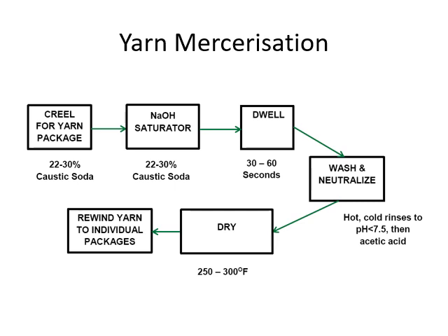In the same extended or stretched form of a hank, the yarns are washed and neutralized. At the time of washing, very hot water up to boil is used, followed by cold rinses, and then it is neutralized with acetic acid, so the pH of the extract of the hank should be near neutral.